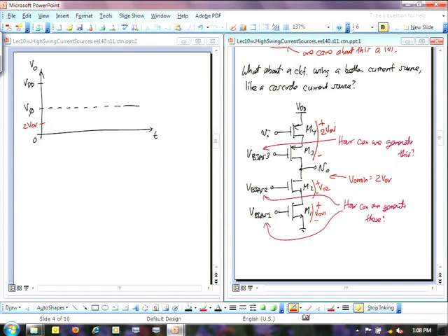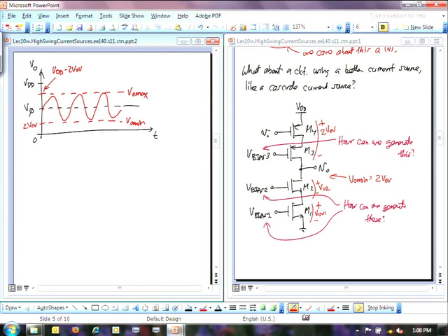Okay, so this point right here, the top floor of this is going to be determined by VDD minus these overdrive voltages. And so then I could say this is the best I can do with this. I could put a sinusoid here that's still linear between those two. Right? This will be V out min. This will be V out max. And you can see from my picture here, I'm starting to use up significant real estate in terms of my swing, in terms of my power supply, right? Just with these 2 V overdrives there.